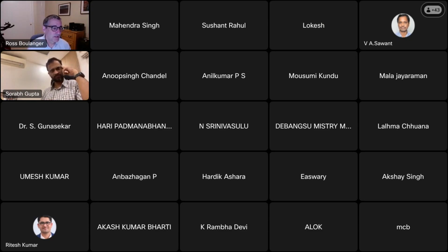So a modest amount of plastic fines. You might log the material as a silty sand, but the silt has just a little bit of low plasticity to it. And the tip resistance in the CPT comes down much quicker than it does in the SPT. I don't know if that maps with your experiences, but I've seen bigger differences once we get into those.